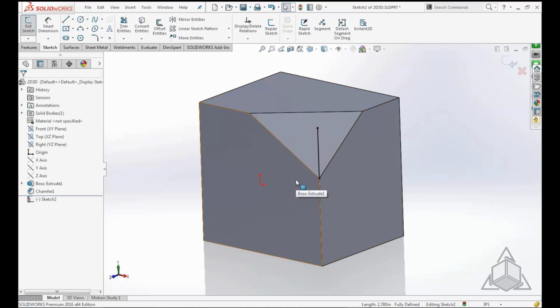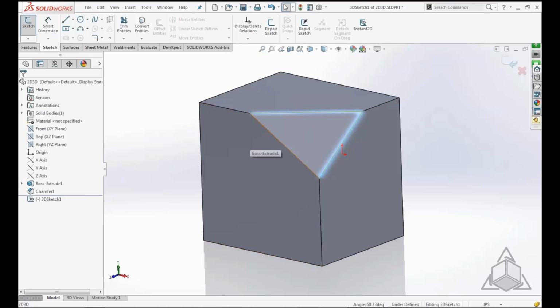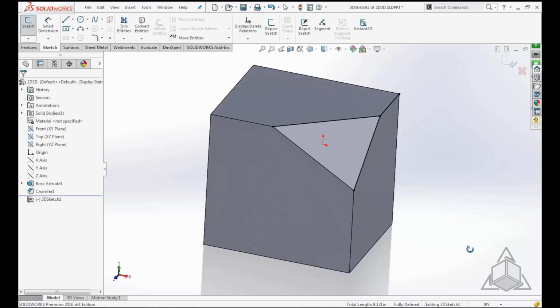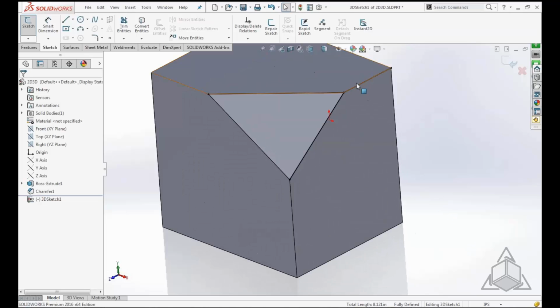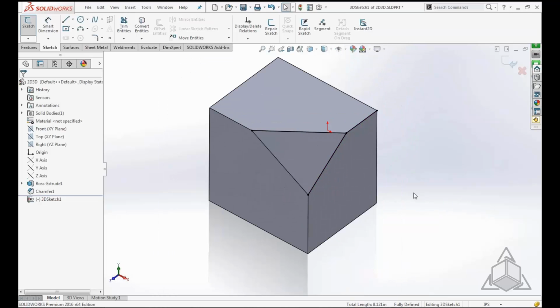The reality of it is some sketches, some things that you draw really need the 3-dimensional piece, needs that Z depth as well. So for a 3D sketch, I'll just get rid of this one here, you have that ability. If I create a 3D sketch and start to convert multiple entities that wouldn't necessarily be on the same plane, all those directions are adhered to. So I got some things going in a Z direction, some things going in X and Y, and I have all 3 preserved directions. That's really just from a general standpoint a difference between 2D and 3D, as I now have that 3rd dimension.